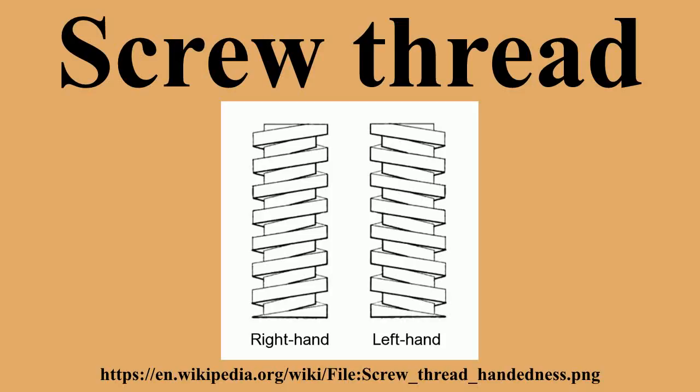Threads can be truncated a bit more, yielding thread depths of 60% to 75% of the .65p value. For example, a 75% thread sacrifices only a small amount of strength in exchange for a significant reduction in the force required to cut the thread.